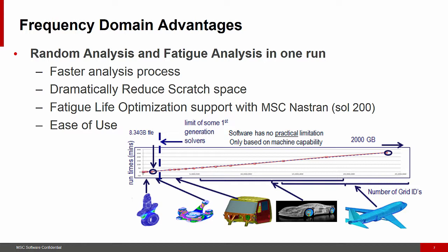Most importantly, when it comes to fatigue life and damage calculations, the frequency-based approach offers far more qualitative information about the structural response. For example, the transfer function itself provides unique information about how and why the structure behaves in the way it does. It gives us a lot of options and information about the fundamental characteristics of the structure. Another benefit of using fatigue calculations inside MSC Nastran and Patran is the ability to optimize the results using the damage or life constraints in solution 200.